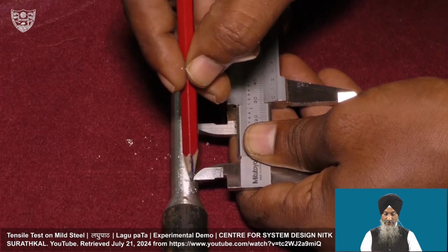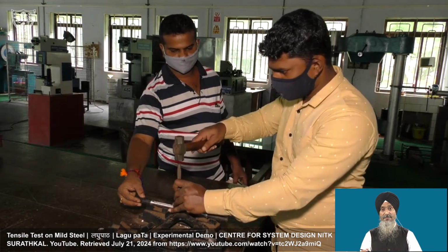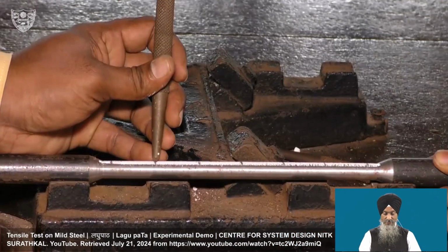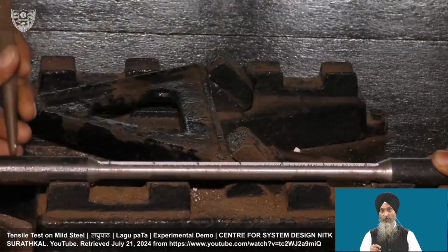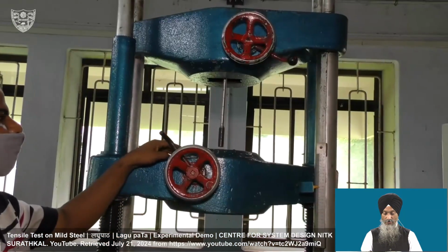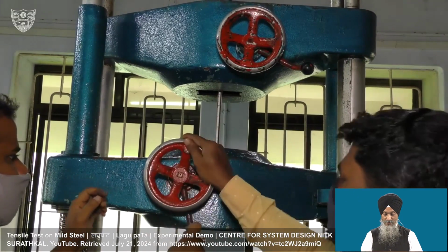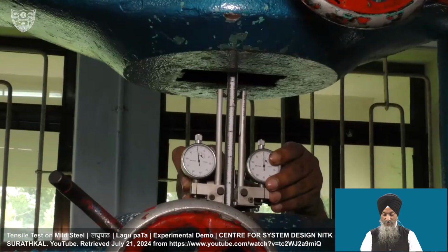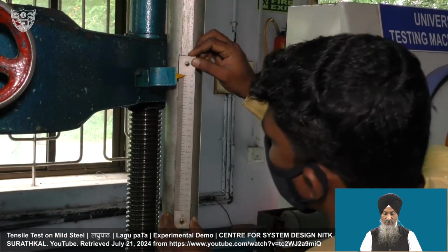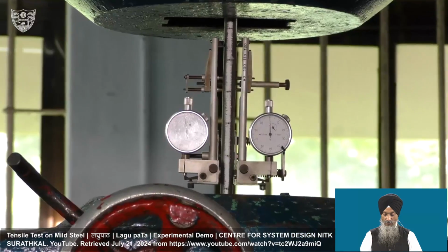Punch marks are made at the extreme points, and these punch marks are made at a distance of 2.5 times the diameter of the specimen. It is 2.5 D. I will show you in the simulation as well. You see the punch marks are being made here, one by one, and then the test specimen is fixed in the cross heads, and the adjacent cross heads are moved now. Now we are locking the specimen here. The extensometer is then mounted so that we also measure the elongation, and these marks will show you the elongation. Now the machine is also set at 0.0. So now the machine is started for gradual application of load.